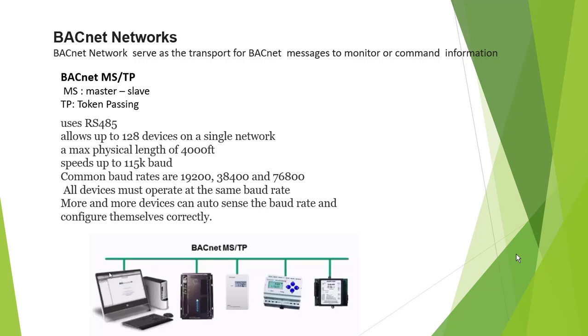BACnet network just transports the BACnet messages to monitor communication information. Most BACnet networks use BACnet MSTP. MSTP means master-slave token passing. It looks like Modbus, or similar to Modbus, but it's much more powerful than Modbus. It uses RS485, the same as Modbus. It can use up to 128 devices on a single network.